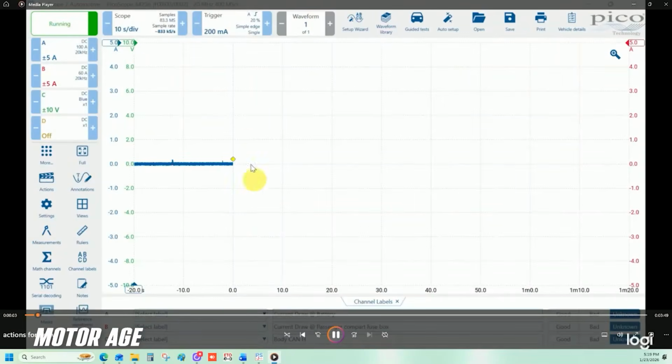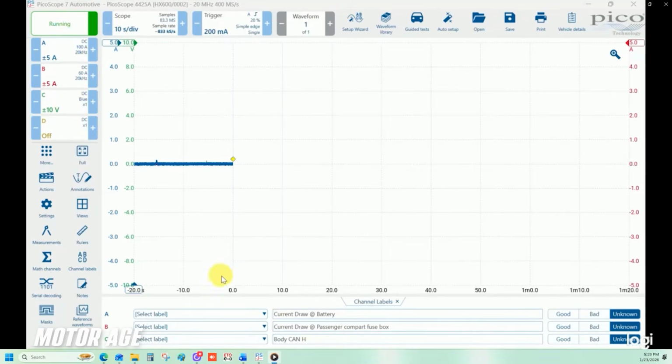But I want to show you something different where this becomes tremendously more powerful in more of a real world situation. We've got a newer model Toyota truck, and we're monitoring the amp probes very similarly to how I did today, except rather than bump a seat switch, we've walked over and grabbed the outer door handle and woken up the medium speed CAN bus network, the body bus, to simulate a parasitic drain that could happen if we had a handle that was going wonky. Maybe it had some water ingress and was going nuts every now and then. So I do want to show you a little bit of a video and a walkthrough of a capture we did. So the first thing we're going to want to do is set up our channels appropriately.